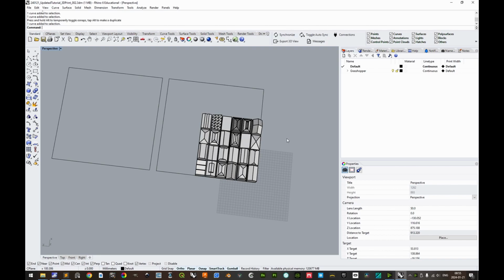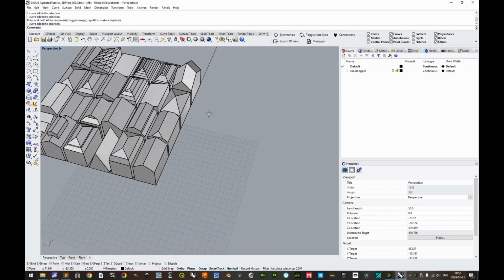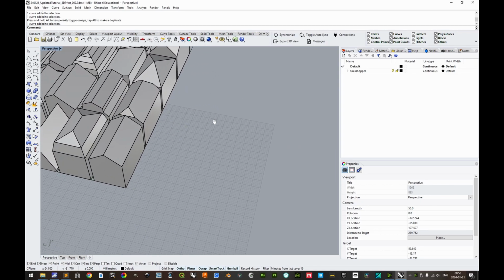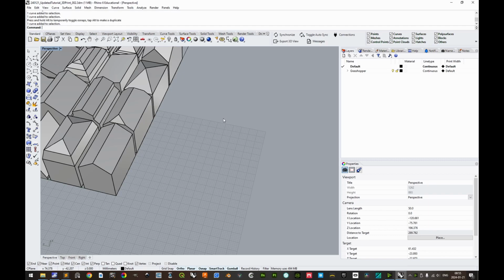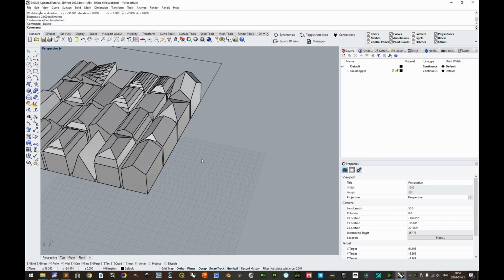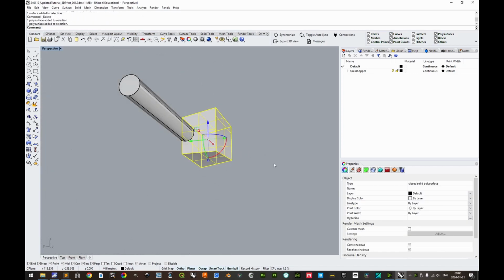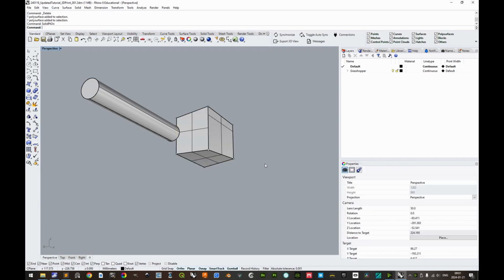Before exporting, we will briefly touch upon some pitfalls which may be encountered. 3D printing is a precise fabrication method, but there are some physical limitations when it comes to the reasonable level of detail of your 3D printed objects. To make sure that a given object actually can physically adhere to the workbed and does not come off during printing, it is recommended that its bottom surface is not thinner than 2 mm in width. All bottom surfaces must be completely flat.